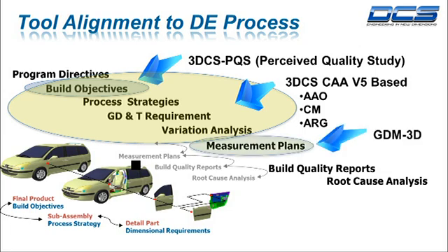The next aspect then is to consider, through the use of the QTM tool set, the ability to generate a measurement plan which communicates not just the intent, but the outcome of the simulations to the plant floor, so that measurements of actual parts can be performed in the same fashion they were during the simulation process.